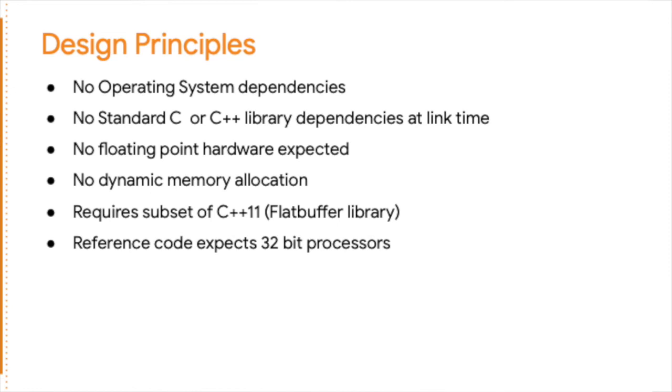And the design principles behind this were we wanted no operating system dependencies. This means no file system dependencies, no standard C or C++ dependencies at link time, so that means no printf even, because printf alone can easily take up just 20 kilobytes, which kind of blew me away when I discovered that. And we don't expect there to be floating point hardware available, because there often isn't on the platforms we're targeting.